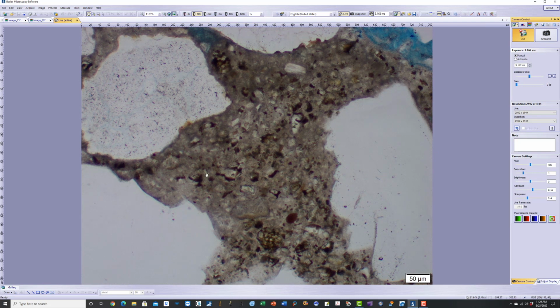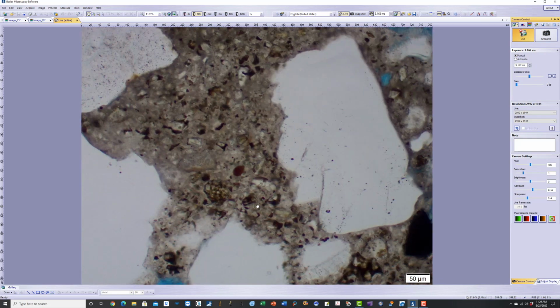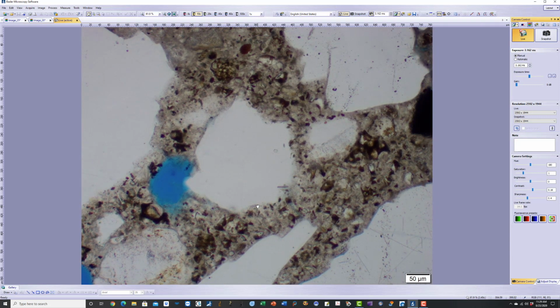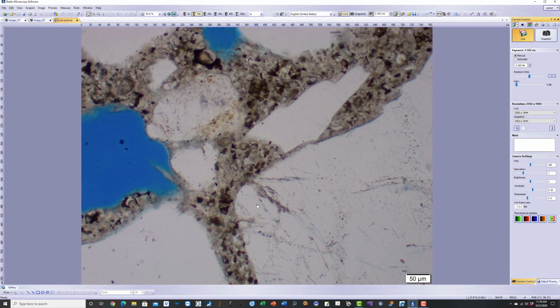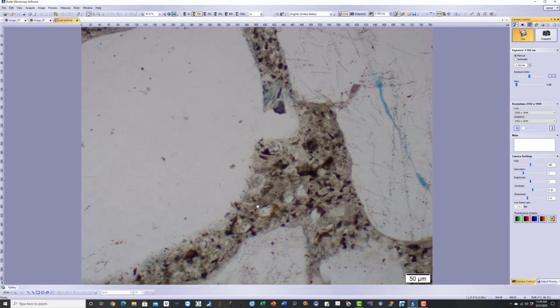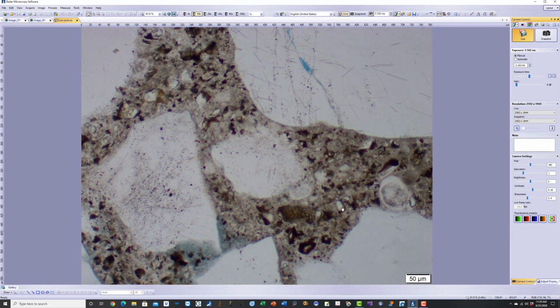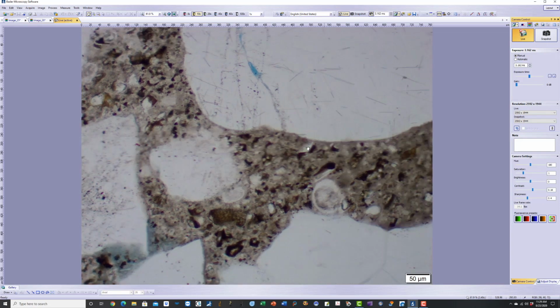You see a lot of residual cement particles and a very dense low water cement ratio paste, where the blue dye didn't absorb to create blue color as the porous areas do. So this area at the very end of the jointing mortar, the degree of hydration is much lower than the majority of the mortar. You see a lot of residual cement particles in the paste. Belite, alite with ferrite, belite with interstitial ferrite, all the residual cement particles and the very dense paste you can see at the